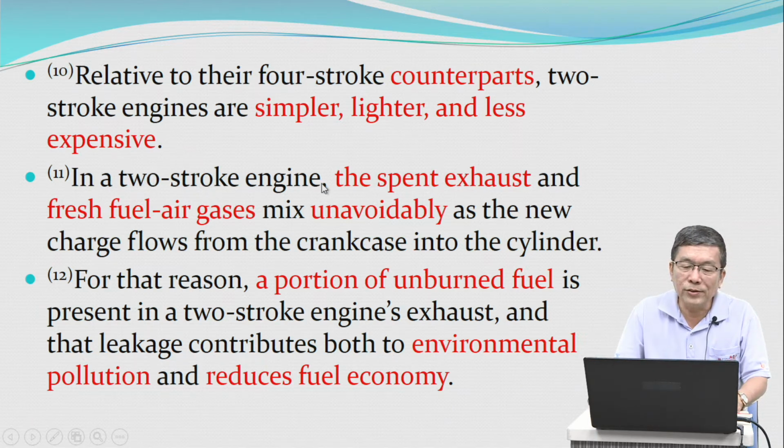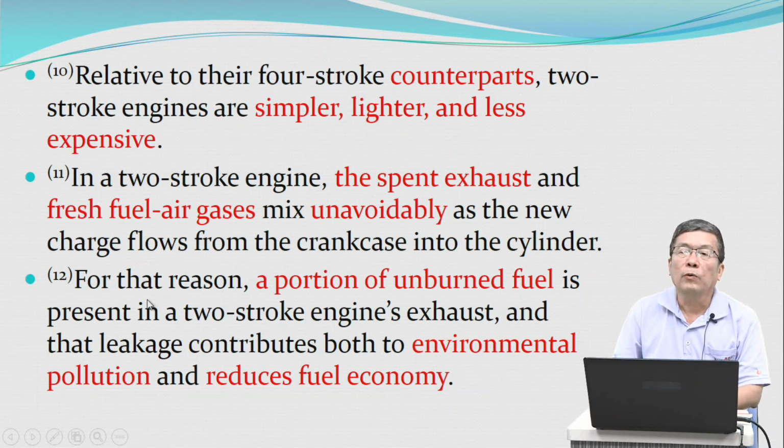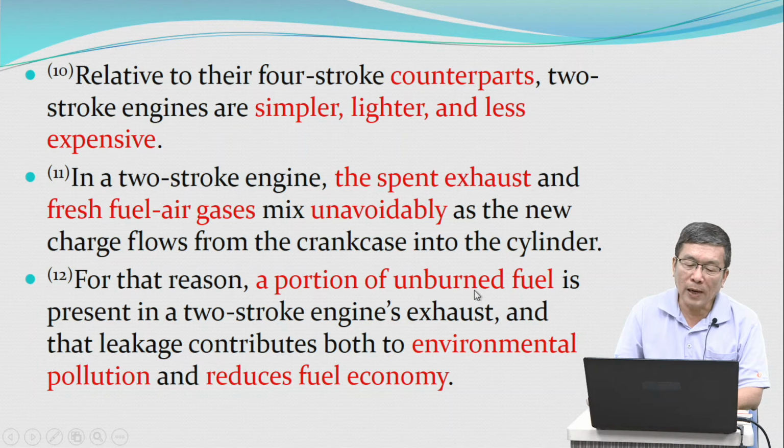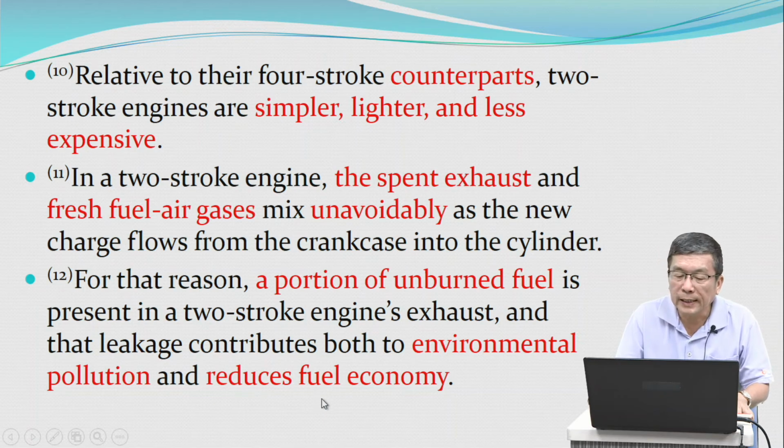In a two-stroke engine, the spent exhaust and the fresh fuel-air gas mix unavoidably as the new charge flows from the crankcase into the cylinder. For that reason, a portion of unburned fuel is present in a two-stroke engine exhaust, and that leakage contributes both to environmental pollution and reduced fuel economy.